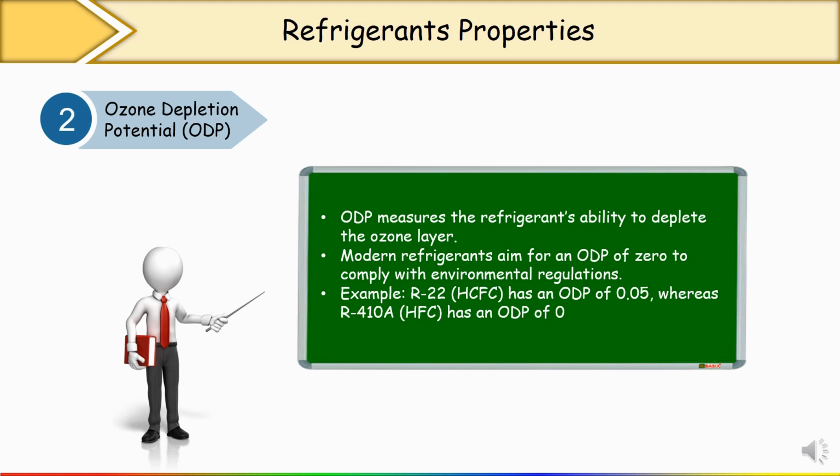So that is why here we prefer HFC. HFC stands for hydrofluorocarbon, which I have already discussed. Nowadays we generally prefer hydrofluorocarbons, meaning instead of using R22 we are selecting R410A because they have a 0 ODP.